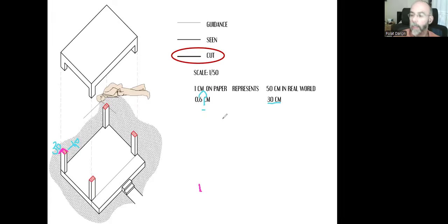That means 8 millimeters perpendicular to my first line and go this way like that for 8 millimeters and go that way like that for 8 millimeters. And here is the fourth and last line of my rectangle. So this is my first column. That's the column that I draw on my paper in 1/50 scale.